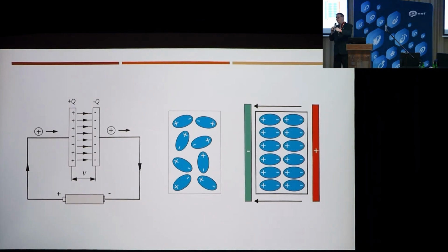And just imagine, ladies and gentlemen, the situation was this. One of his jumpy workers connected the clamps, took the measurement, then right afterward pressed stop and immediately grabbed it to take the clamps off. And he got a jolt through his hands. So the meter had already started the process of discharging that object. Part of the discharge happened through that person.